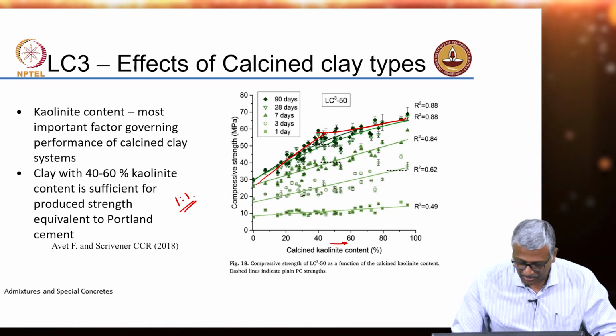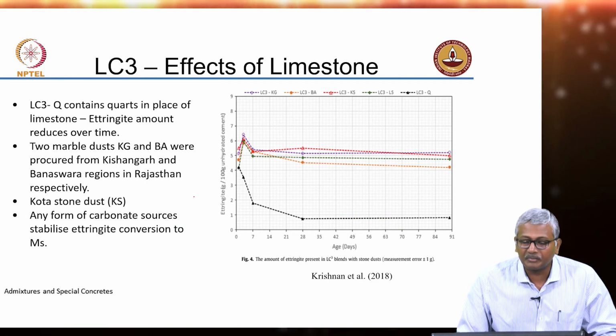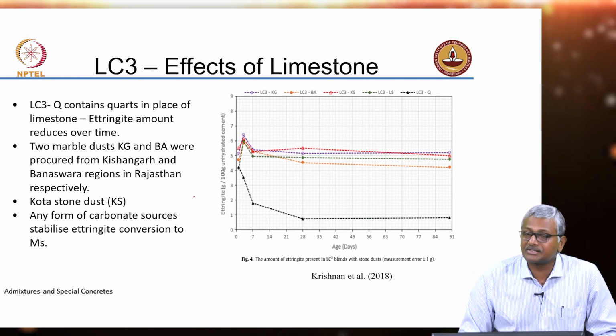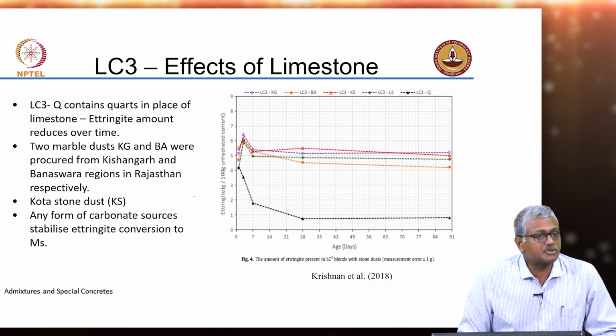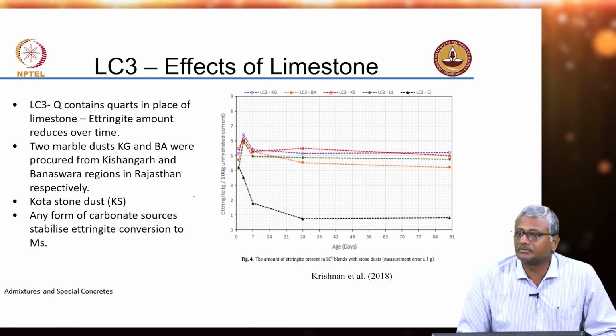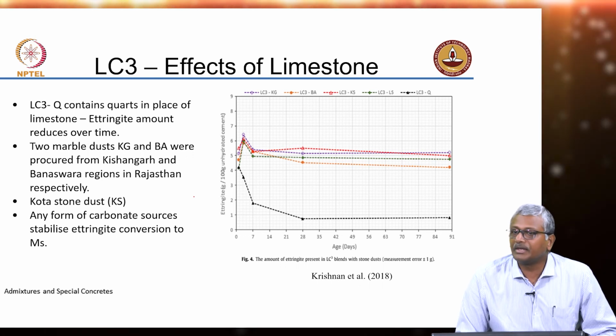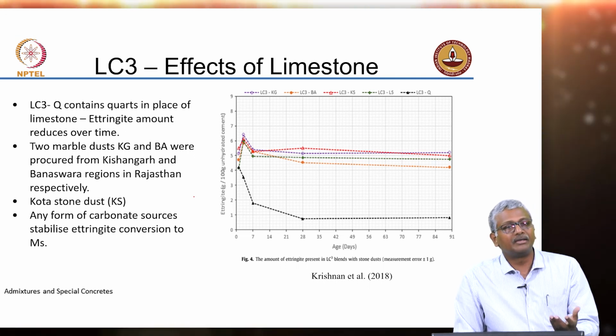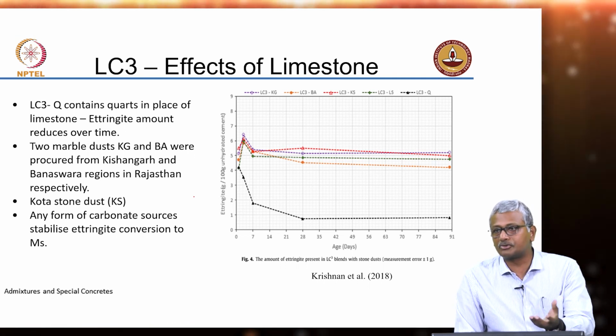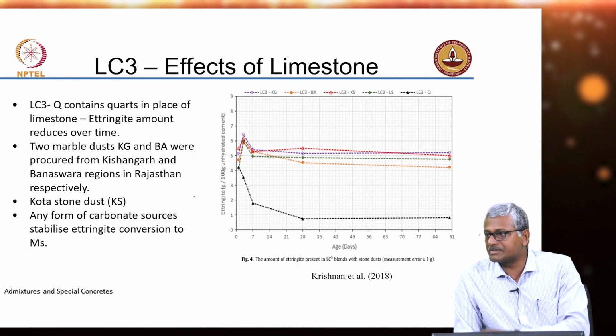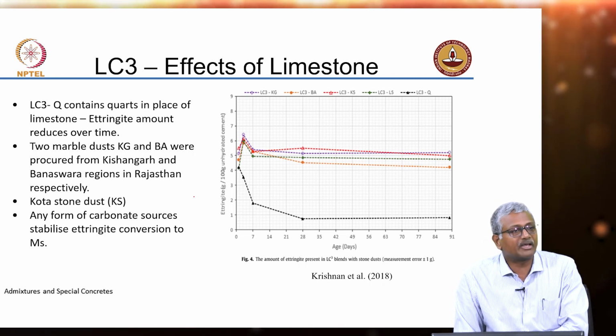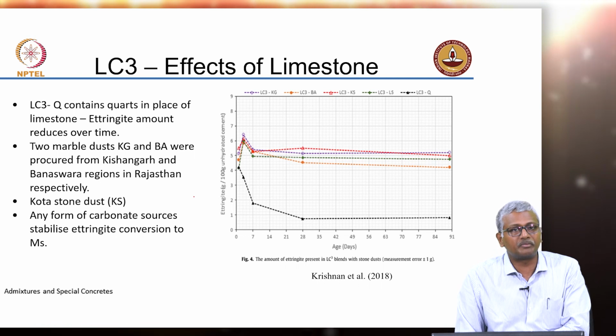Okay, anyway, that is a more involved discussion, we will not go there. But what I wanted to also tell you is that it is not just pure limestone that is required to make such systems. You can start working with impure limestone also. I already told you that only a part of the limestone actually dissolves to take part in the reaction, the remaining simply serves as a filler. So why not start using other limestone bearing materials?